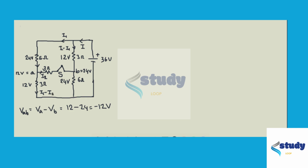Since I2 gets here, and I minus I1 gets here, these two, I minus I1 and I2, combine to give the current across the 6 ohm. So this should be how much? I minus I1 plus I2.